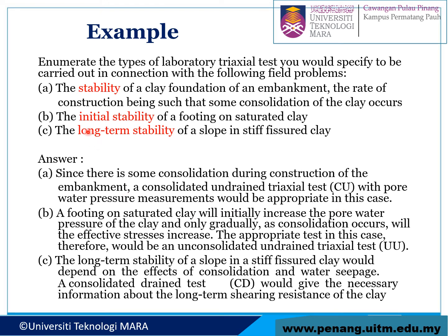For the second case, the initial stability of a footing on saturated clay. The word initial stability for saturated clay is obvious. This one is of course the UU test. A footing on saturated clay will initially increase the pore water pressure of the clay. As consolidation occurs, the effective stresses will increase. The appropriate test is the UU test.